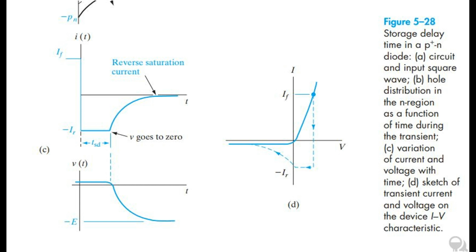After the generator voltage is reversed, at t = 0, the current must initially reverse to I = I_R = -E/R. The reason for this unusually large reverse current through the diode is that the stored charge, and hence the junction voltage, cannot be changed instantaneously. Therefore, just as the current is reversed, the junction voltage remains at the small forward bias value it had before t = 0. A voltage loop equation then tells us that the large reverse current, E/R, must flow temporarily.